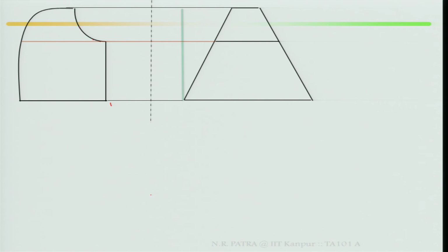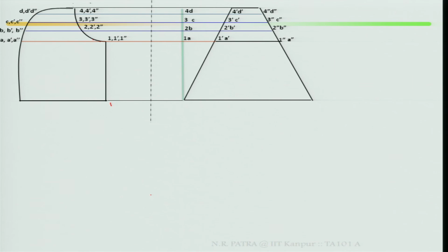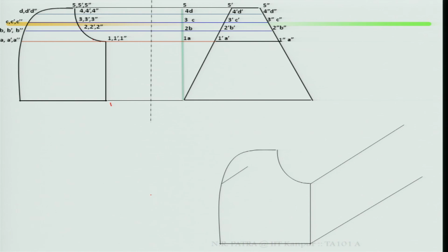Once again I am explaining: take a reference point, reference line, then mark your oblique surface, different sections, mark the points. Once your front face or front view has been given, in oblique projections, front view is your true shape. So finish your front face or front view, because this is your true shape. Then go to your depth directions, then mark the same way, the way the sectioning has been marked and points have been located.